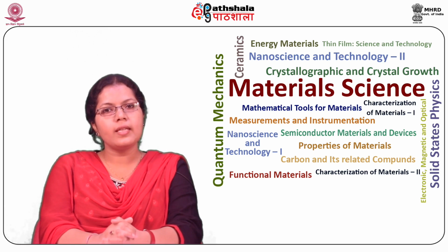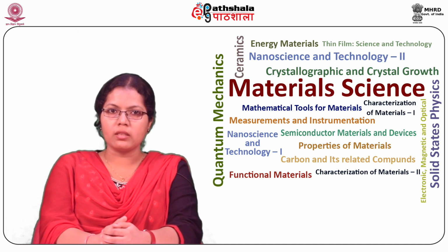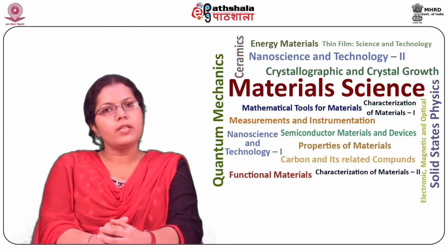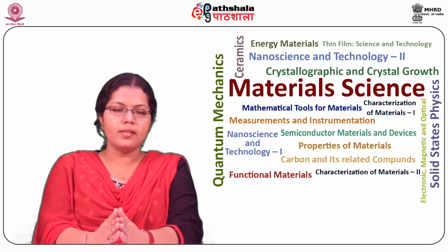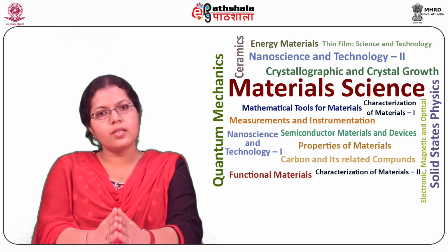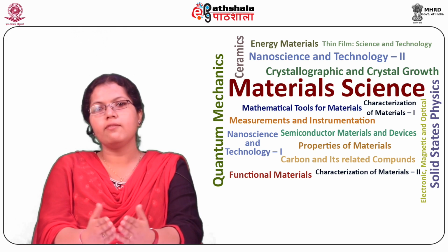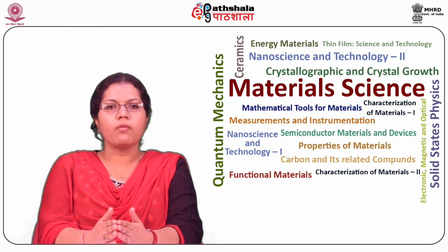We also discussed the various materials suitable for use as resistors, such as manganese, constantan, nickel chromium alloys, and gold chromium alloys. Secondly, we studied the inductors. We saw that for the designing and construction of inductance standards, a few considerations must be taken care of, such as the design and construction should be such that a rigidly standard accurate formula exists relating the value of inductance with the physical dimensions. We discussed the formers of inductance coils, which are made of marble.